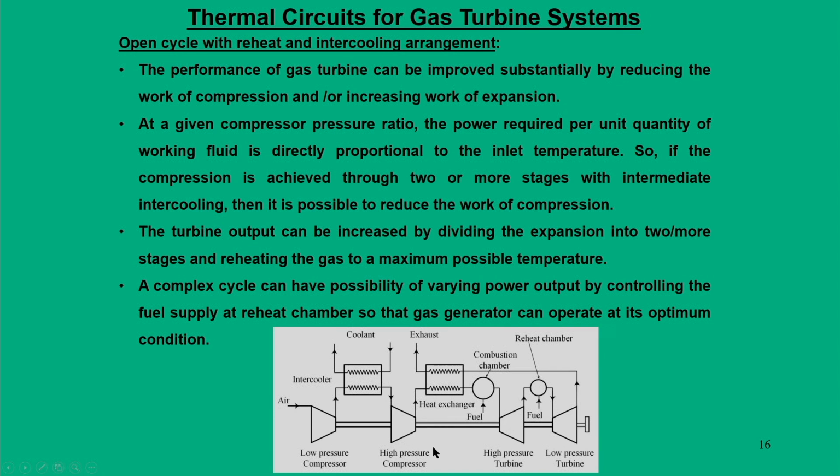Thermodynamically it is proven that in a single stage of expansion over a wide pressure range, instead of going in a single stage, if you go for multiple stages, then your efficiency will go up and power output will also be higher. So, staged expansion is more efficient than a single expansion.